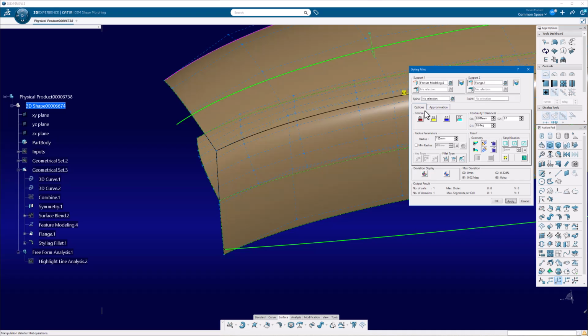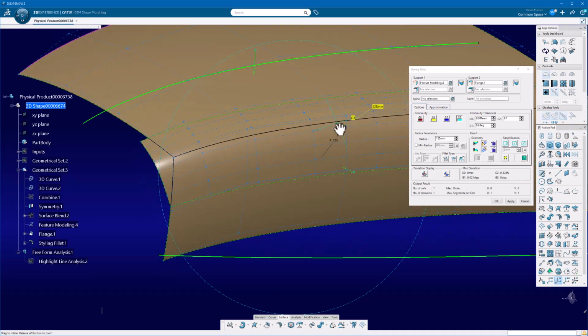What I typically do in a case like this, I don't ever trim the supports. I don't say ever, but more likely not to trim those supports. Extract those curves and maybe use those curves for other things. Or I draw in the curves that I want and then put in that blend in different ways.